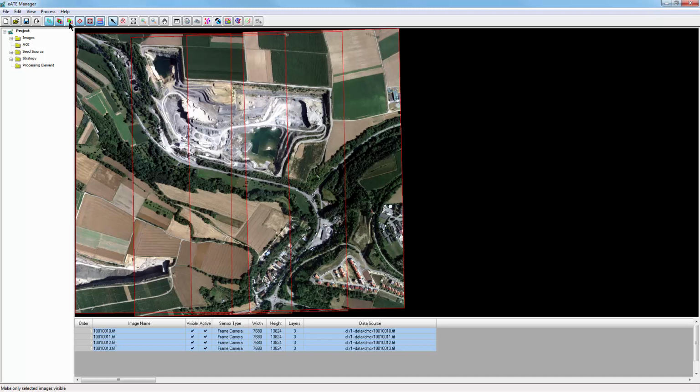The viewer shows the raw images oriented based on the triangulation results. Terrain extraction utilizes the parallax or relief displacement between images calculated during triangulation. It's this offset between the images that allows the software to extract the terrain value.